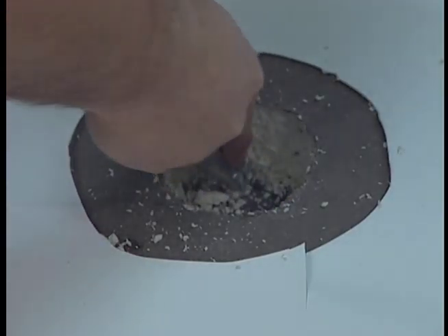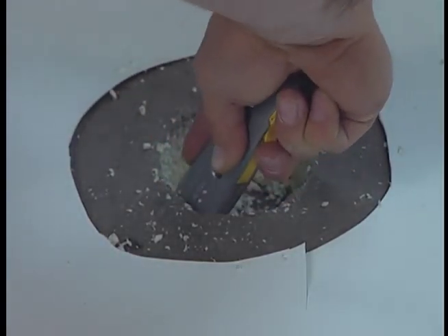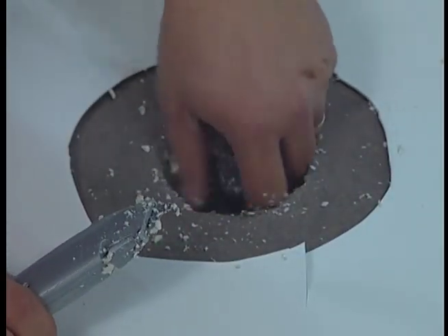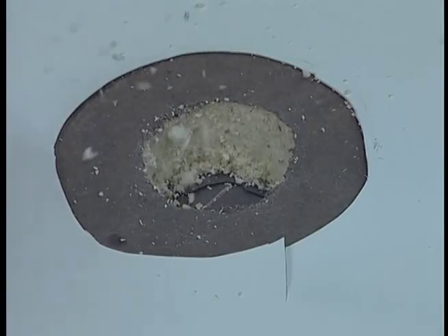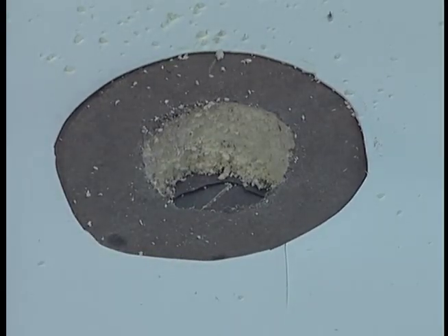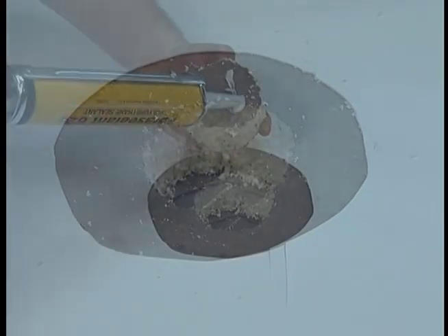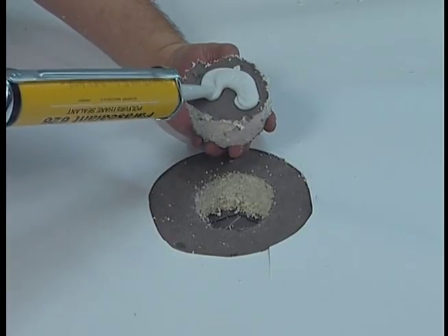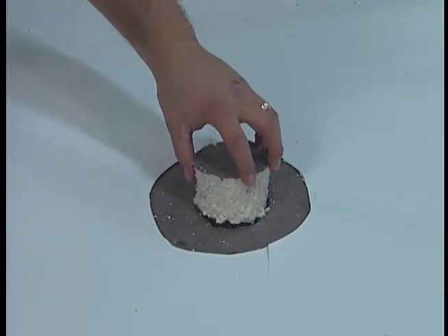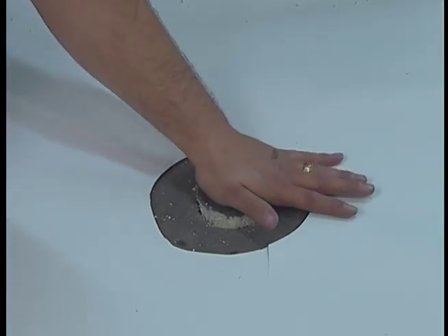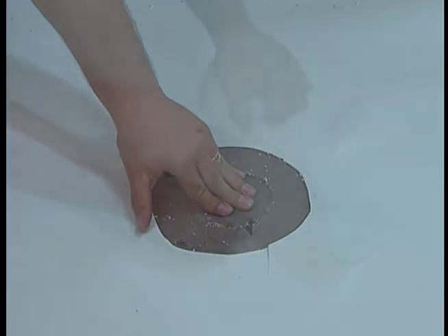Do not cut through the original insulation and do not penetrate the existing vapor barrier. Remove the debris from the hole. If you removed insulation, fill the void with new insulation. Apply sealant to the underside of the insulation plug to hold it in place. Of course, if the original roof has no insulation, you won't need to do this step.